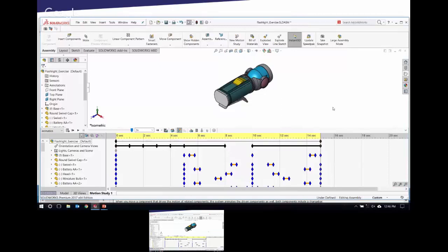Yeah, if you do a top-down part that resolves, right? So as these get apart, the actual part is built in the context of the assembly. Where instead of saying it's this tall, you say it's from this point on this part to this point on this part. When the parts move, the part resolves every time. When you run through the animation, each frame it will resolve that part. The part looks like it gets longer when you're done with the animation. Okay. So you do springs like that too, is what a lot of people do.